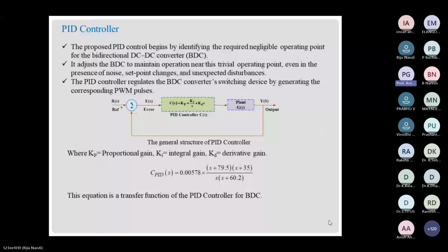KP, KI, KD are only related to the PID controller. Suppose you want to design a lead-lag controller using a soft computing technique. In that case, there is no KP, no KI, no KD; it will just be gains. So instead of KP, KI, KD, you can consider different gains, K1, K2, K3, like that. That will be a better approach, and any kind of algorithm can be used, no issue. Thank you, sir.